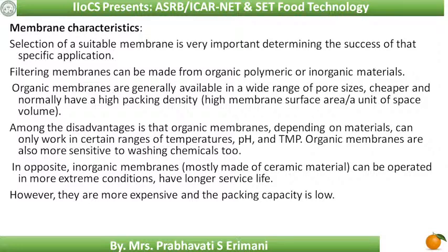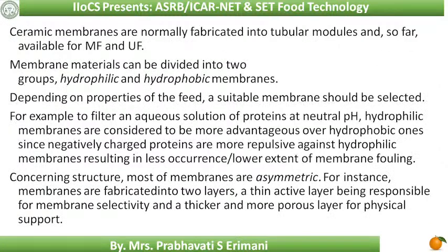Opposite to this are inorganic membranes, which are made with ceramic material. They can be operated in more extreme conditions, and they will have a longer service life also. But they are more expensive, and the packing capacity is low. Some such advantages and disadvantages will be there. These ceramic membranes are normally fabricated into tubular modules, and now are available for microfiltration and ultrafiltration.